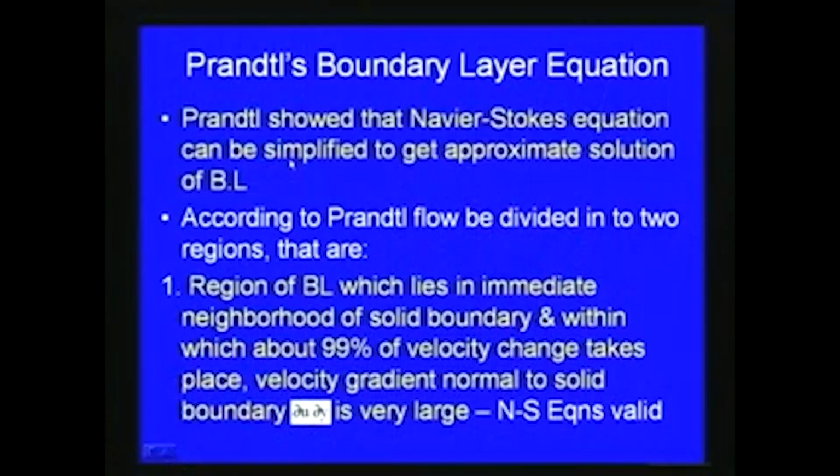layer flow is concerned. So the initial theories on the boundary layer were proposed by Prandtl, and then various other scientists like Blasius have solved the boundary layer problems and tried to get expressions for velocities, shear and other parameters. So first we will see Prandtl's boundary layer equation, and then we will discuss how Blasius got his solutions, and then we will see the momentum integral equation as far as the boundary layer is concerned.